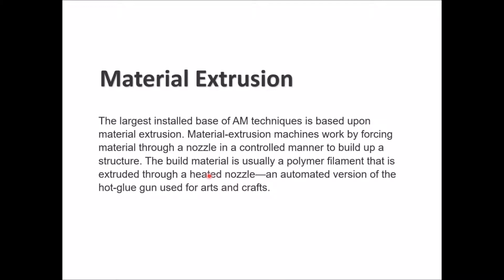The build material is usually based on a polymer filament. This filament is exposed to heat, melts and gets extruded through the heated nozzle, and you can imagine it like a hot glue gun, but in a programmed and engineered way.